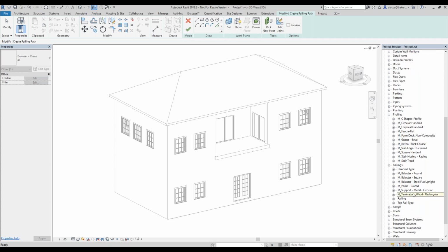Okay, so you get a profile family in which you can specify that it might be a railing profile family, and with that profile you can generate your rails and your handrails and so on. Under the railing you can see there's a handrail type and all of these balusters that you see there. If I click on the railing down here, it gives you the whole family that is built up to form the balustrade that you would eventually draw onto your space.